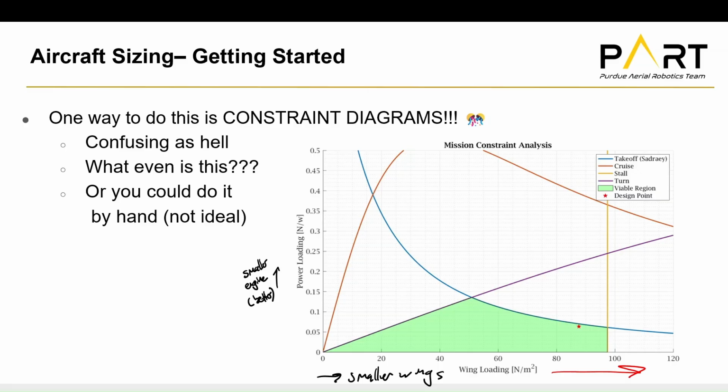Okay, so we have a relatively short runway length we're looking at for this specific diagram. So that's very much an active constraint. And an active constraint is every one that impacts our viable region. So our viable region is what's below these lines. All right, it's the biggest region you can make, bounded by your active constraints.